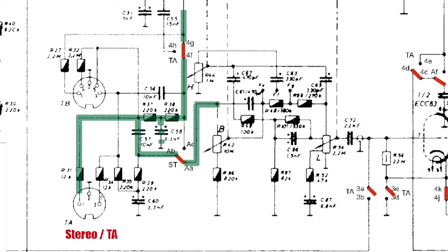The right channel does basically the same thing. It comes up here, goes across there, goes up here, there's the tape, forget it, it goes across this 10 nanofarad capacitor, and it now has the path that we've seen before going upwards. So this signal, which is the full right channel, the purple, is joining with the low frequencies of the left channel.